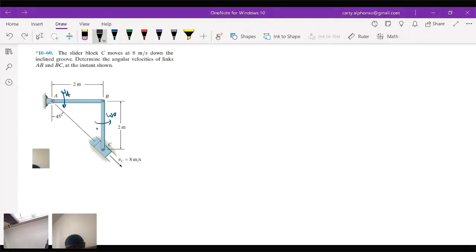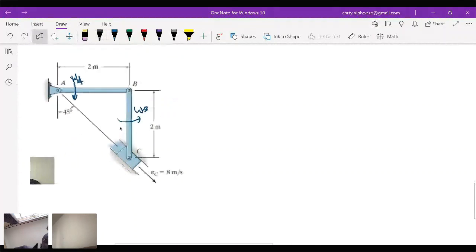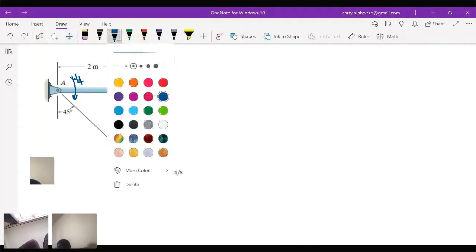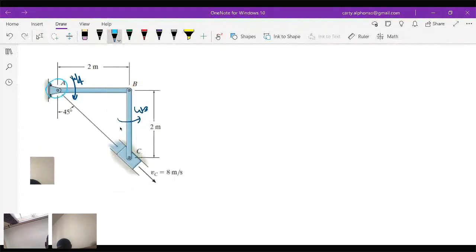All right, so what I'm going to do is draw them arbitrarily because I know the physics. When you know the physics, you can do this. I always start from the fixed axis point because it's obvious what the velocity is going to do. If this guy's going to push down like that, then the velocity of B has to be going, let me use green, pointing straight down for this motion to happen for A. Does that make some sense? I don't know what the value is, but I do know the direction. And then obviously they told us that the velocity of C is going like that.